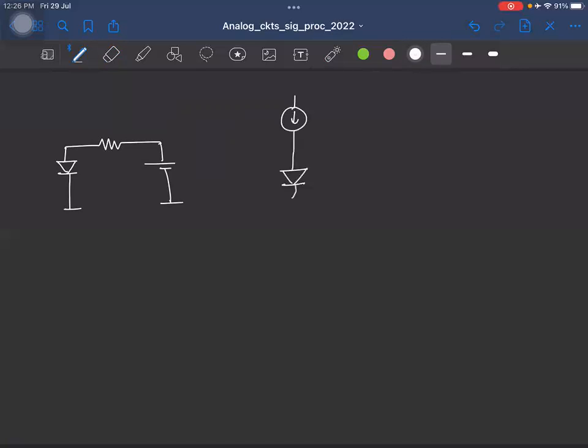I'll do this. If I pass a current I1, and if I measure this voltage, even if I increase the current I1, you know the VI characteristics of the diode, it will look something like this. So even if you increase the current a lot, say from here to here, the voltage variation is very small. So this is one way in which you can get a decent voltage reference, which is roughly constant, not completely constant, but more or less.